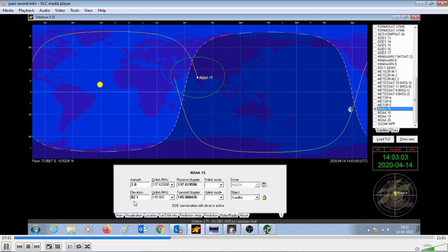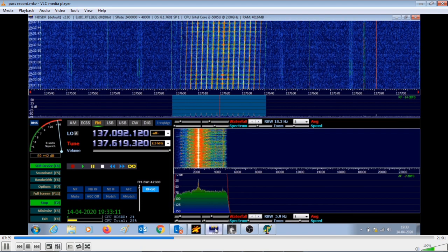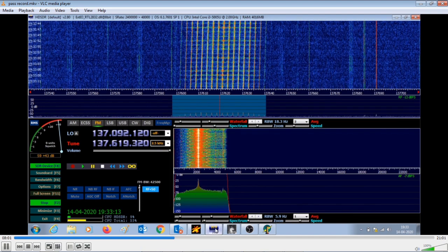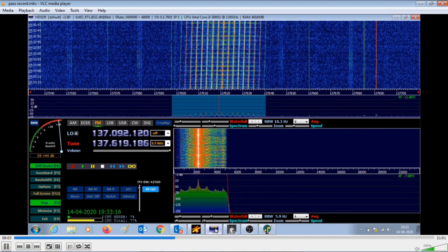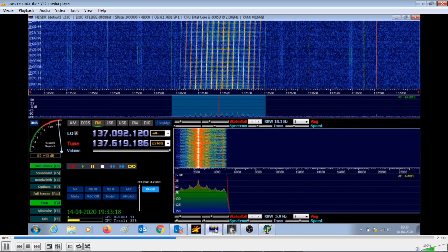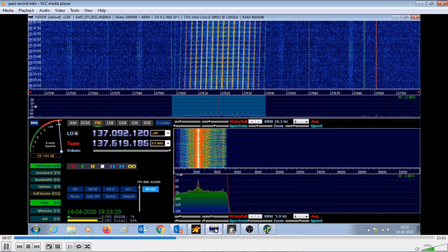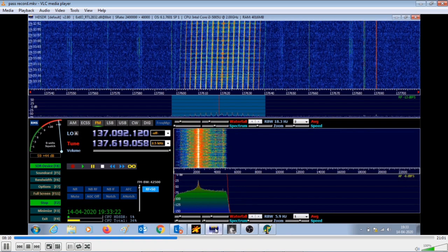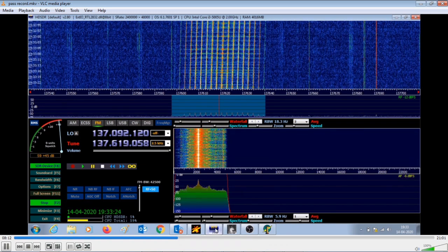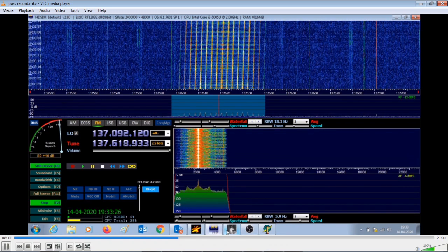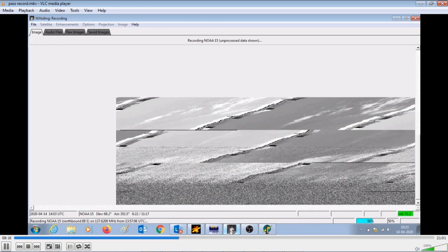It is important to keep the antenna away from different structures at a height of at least 10 feet. And also it is important that none of the applications and softwares are running in the background. Considering all these points, you will get a very nice recording of the image.